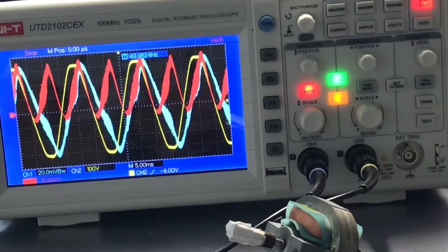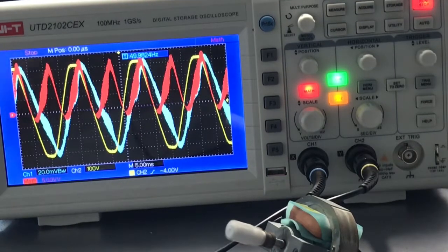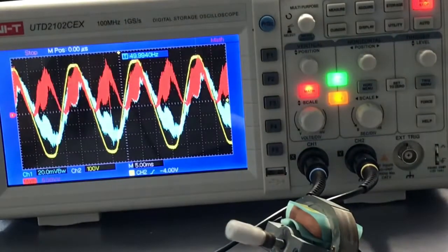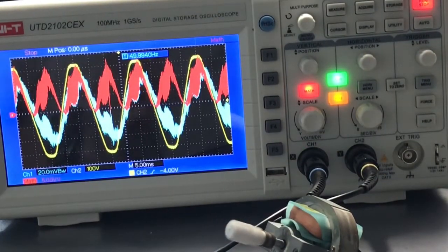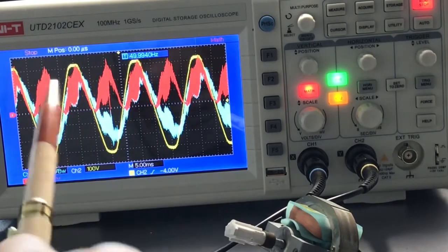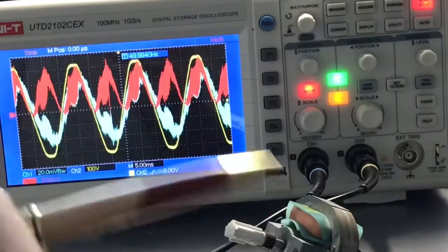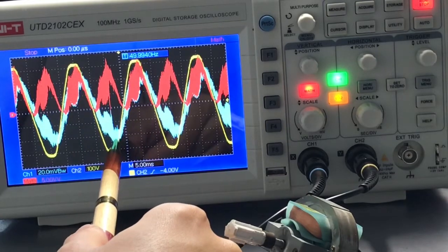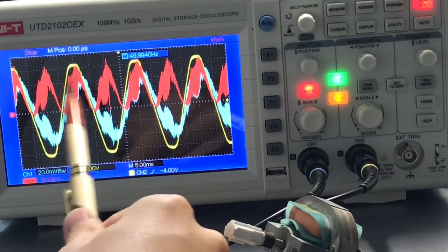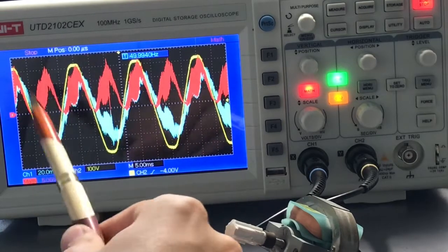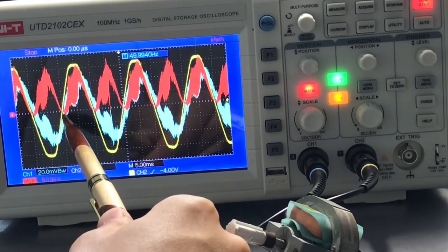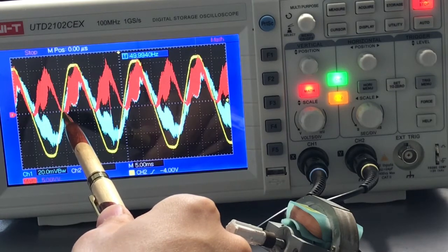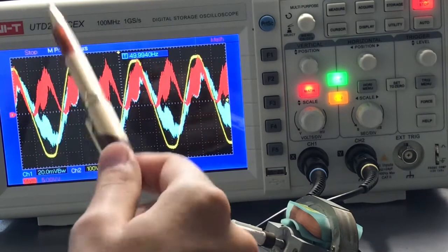So right now I will connect the whole circuit with the compensation capacitor, register the waveform, and that's what you can see. Of course, there's a lot of noise in there because of this cap added, because a lot of line inductances is added, but anyway, current is a bit smaller right now, and it's shifted to the left a bit because of the capacitance. So right now we barely have the power that is returned to the source, and this is what we want to achieve.